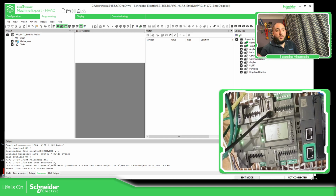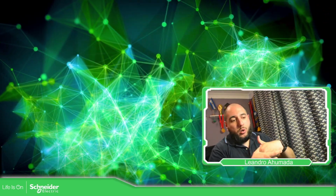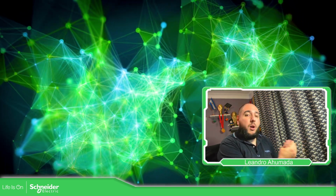Now you can see it is loading the system in the background. Then you should be able to see that it is loading 3 different parts: PLC, HMI, and the connection. And there you can see that I have the 3 LTAs. So I have the source of the PLC updated and the HMI already updated, all in one go. Okay, that is what you need to do once you finish your machine or everything, and just download everything. Otherwise you have downloaded everything in 2 different parts. Okay, so this is how you can download your embedded display application into the M172.